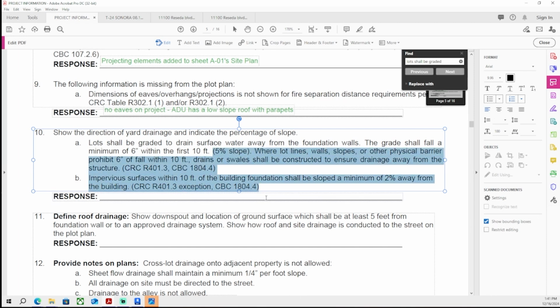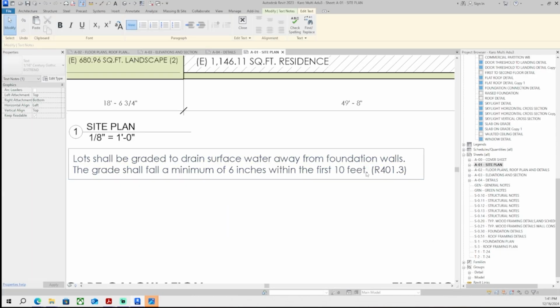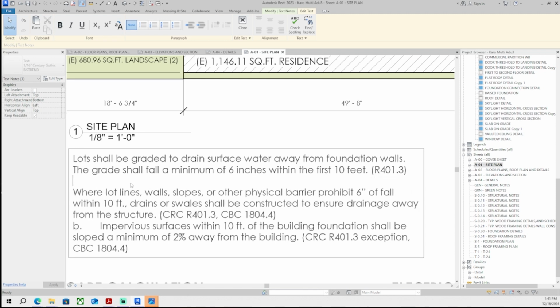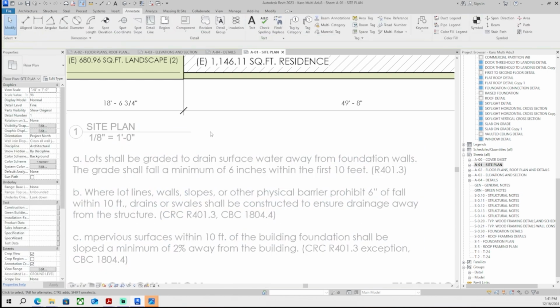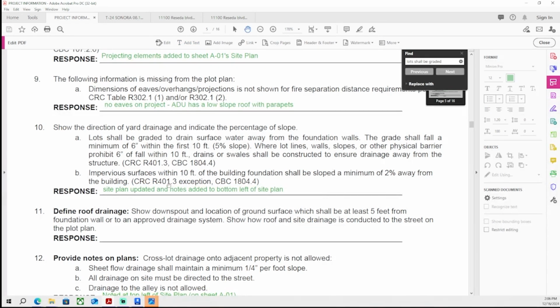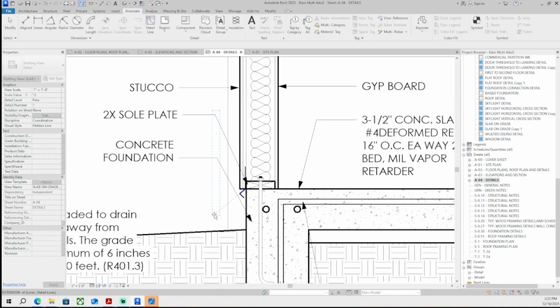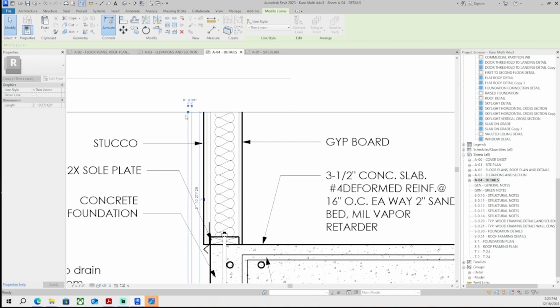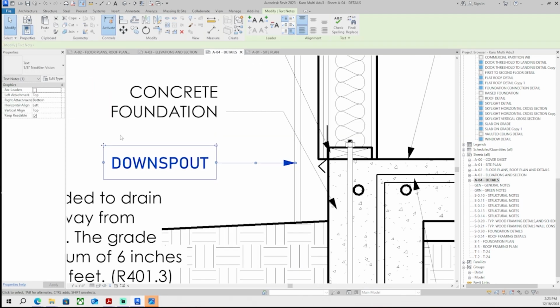Okay, so shower, minimum area, 1,024 square inches with a 30-inch diameter clear turning circle. Yeah, I've got this minimum. Oh, and then there's the site drainage. Site drainage is very important. We don't want the water draining into the habitable space. So we do two things. We show these in the drawings, and secondly, we type these out as notes. And again, the notes are worded differently depending on your jurisdiction. You need to give your city the notes it wants for that city.